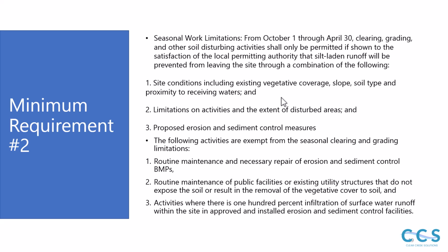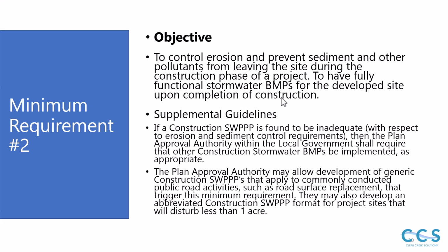The following activities are exempt from seasonal clearing and grading limitations: the routine maintenance and necessary repair of erosion and sediment control BMPs, routine maintenance of public facilities or existing utility structures that do not expose the soil or result in the removal of the vegetative cover to soil, and activities where there's 100% infiltration of surface water runoff within the site in approved and installed erosion and sediment control facilities.